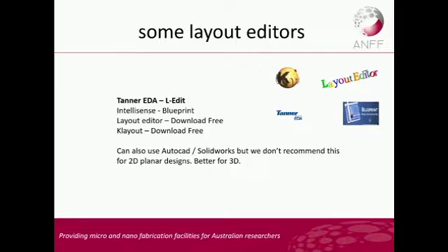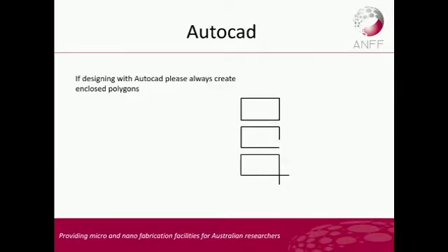A lot of our clients use AutoCAD for layouts, which is probably okay if you're just doing a single mask. If you're doing many, many masks, then it gets a bit cumbersome, and we also have some issues when it comes to writing the masks. Some of these issues arise because our mask writer works on writing polygons. So a polygon is just an enclosed structure, so here it's got 4 vertices.